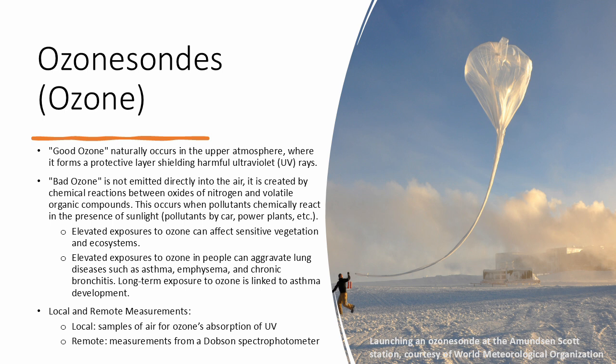Ozone has a peak absorption at a wavelength of 254 nanometers, which is in the ultraviolet light region of the electromagnetic spectrum. Light energy emitted at this wavelength is not able to pass through the ozone. Inside the ozone analyzer, the sample and background air are both exposed to UV light. Both cells, sample and background, have a sensor that measures the intensity of light that passes through the air.